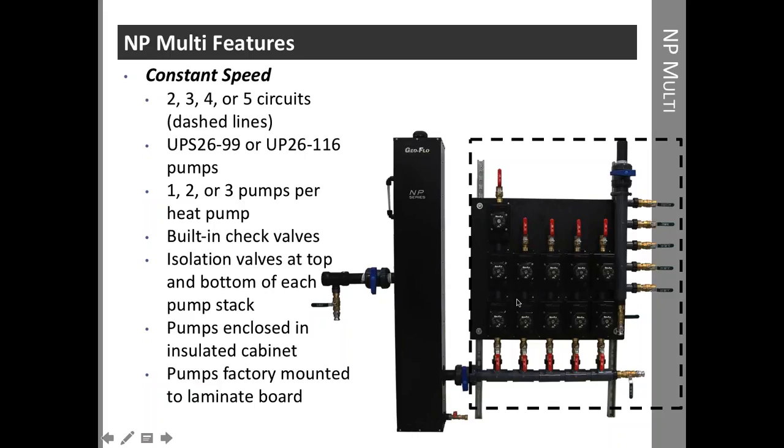This is not one I would recommend just because it's an awful lot of watts. Even if it's 2699 Grundfos circulators, they're about 170, 180 watts a piece. If these were 26 116 pumps, they'd be about 280 watts. So it's a lot of watts if you go with individual pumps. Now, if we only had 1 or 2 pumps per circuit, it wouldn't be as bad. But in this configuration it's an awful lot. So we can choose the number of pumps.